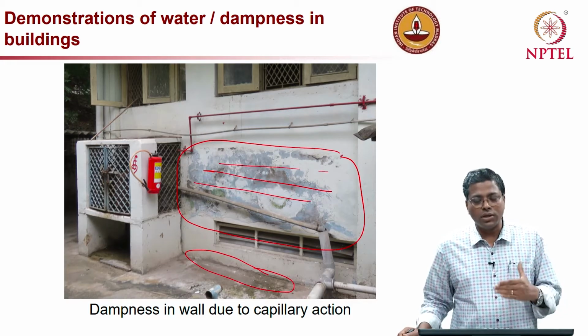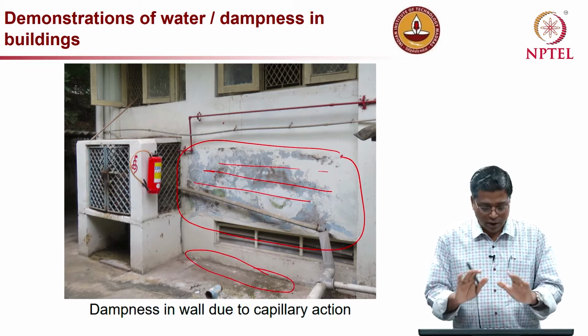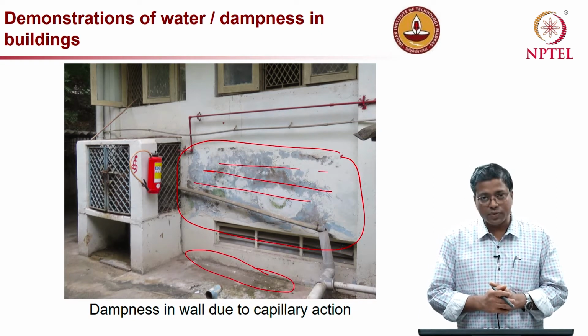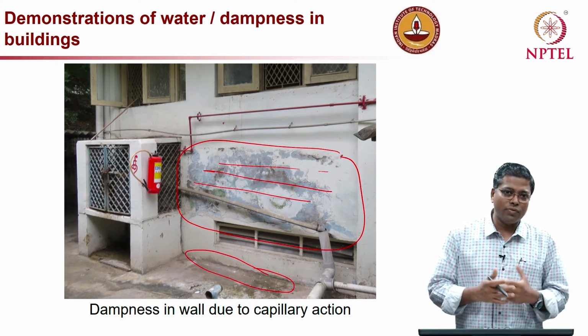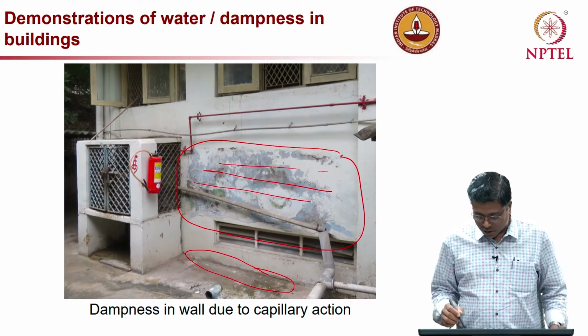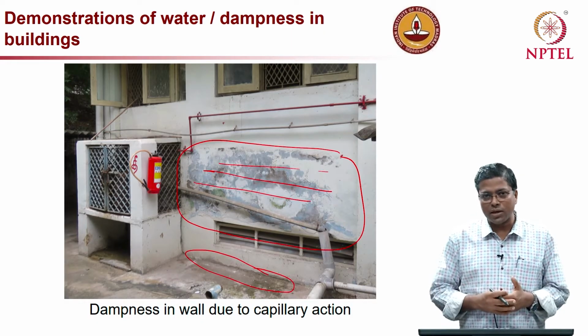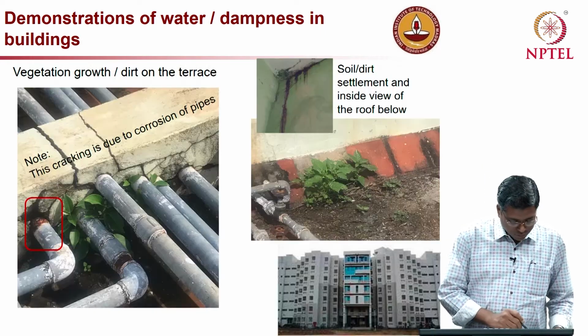And because of all this, to understand where the water is coming from, first you look at how the damage looks, or the pattern of the damage, and then look at what is available near that, where the source of water is. It is very important, and sometimes it might be pipes, sometimes it might be stagnant water, and sometimes it might be just the water from the ground.